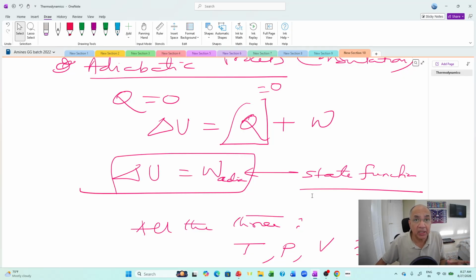But in real study, if you take insulated container, the decrease in temperature is very large. There is a cooling effect as you expand by holding the piston in your hand. I'm talking of the gas. The gas was there at 20 atmosphere. Just you release slowly. Your work is to slowly reduce it. That means you imagine you are having 20 kg sand and you are removing grain by grain. Then even if it is slow and reversible, it is adiabatic.